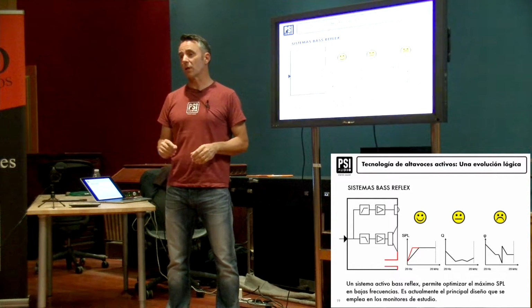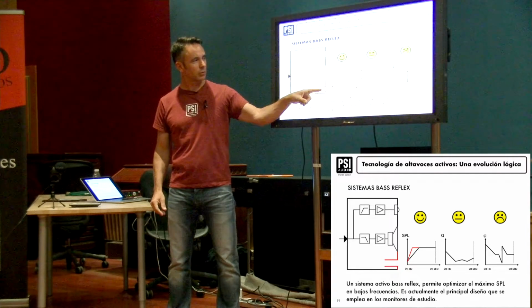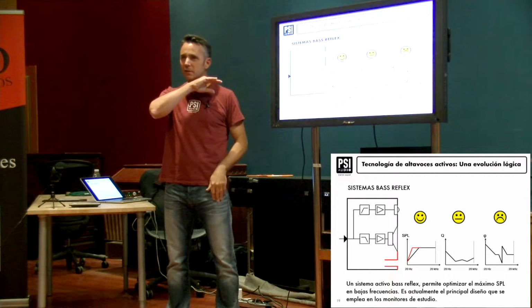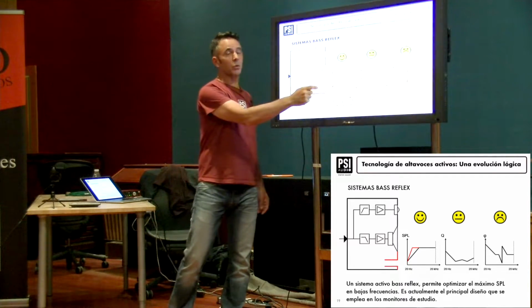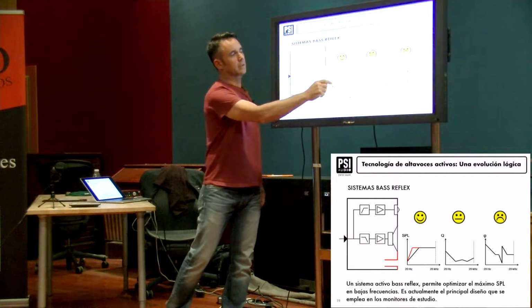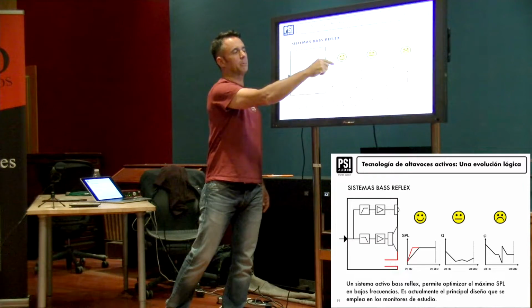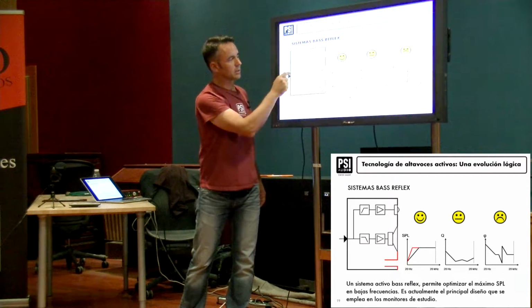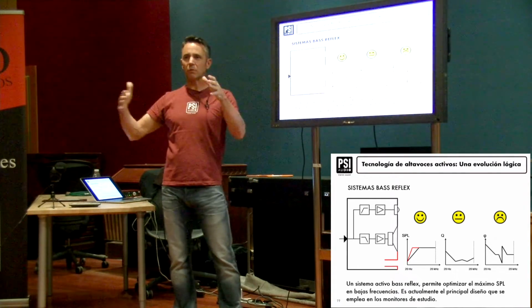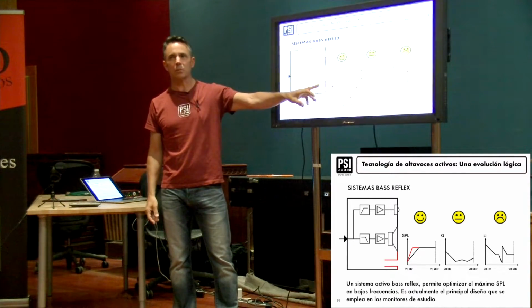What's very important is that it's perfectly adapted, and what comes out of here, here, and here is flat in frequency and flat in phase. And often when you have ported systems or bass reflex, you have a hole and then you have a big bump, so that's what people don't like. Or you have a much too big a distance between here and here, so there's a bit of delay, and that's what you don't like. But it has to be done properly.